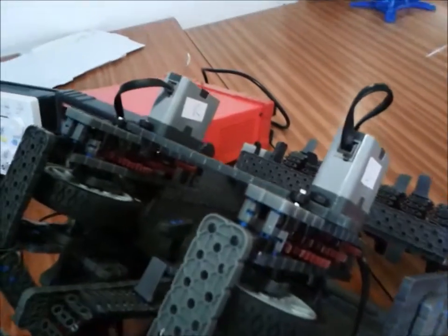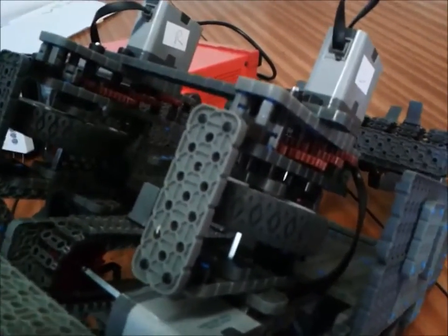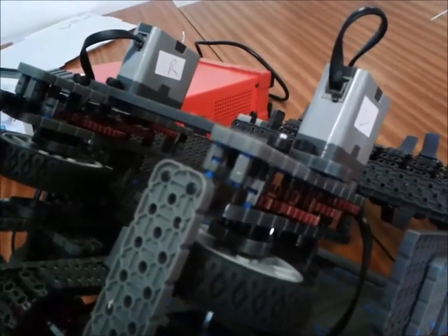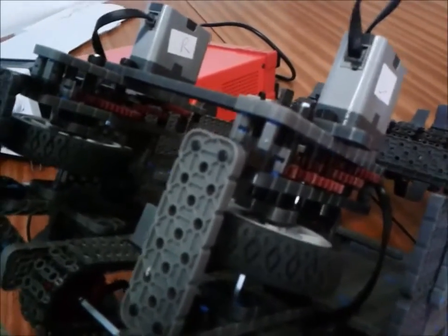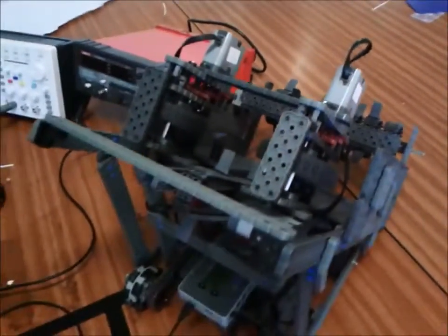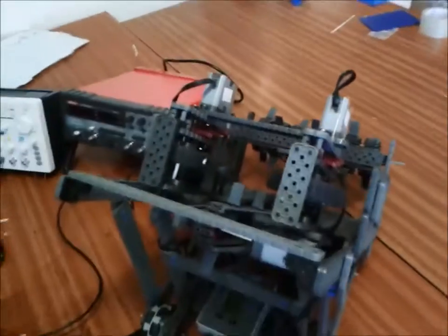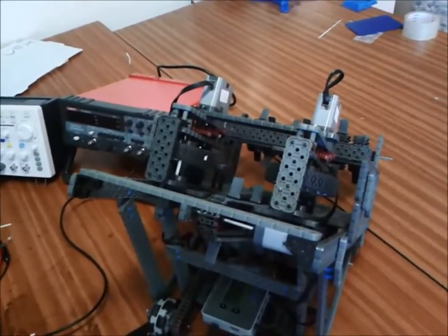That will tell me whether I've got losses in my gearboxes or some inefficiencies here, because if they both turn out to be 120 RPM or thereabouts, no load, and then when I connect them up to the gearboxes I find that one's going quite a lot faster than the other, it may well be that I've got losses in the gearbox I need to look at, something's tight somewhere, so that can help me to improve the performance of them.